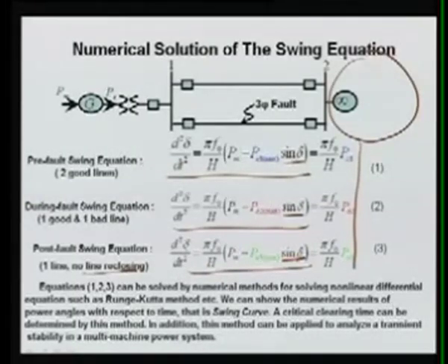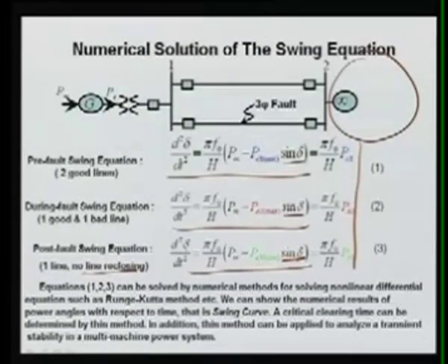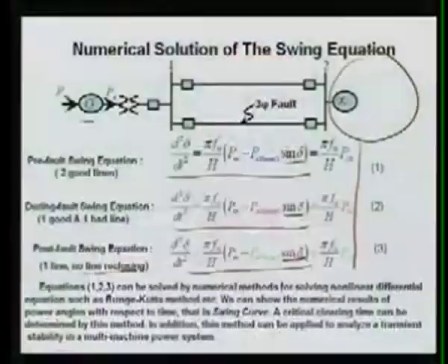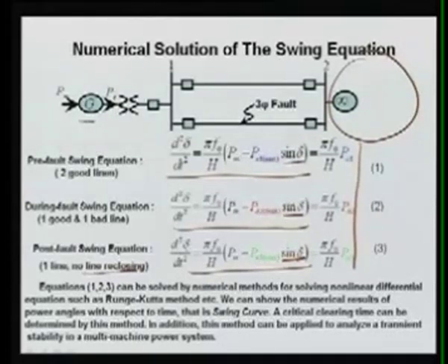In the real system there will be several generators, and again this generator is not a classical generator. A classical generator means a generator which we have modeled in the classical form, taking only the generator with some inertia constant. Then we can go by several orders of modeling of the synchronous machine. It will be equipped with the excitation system as well. It will be equipped with the governing system. So all